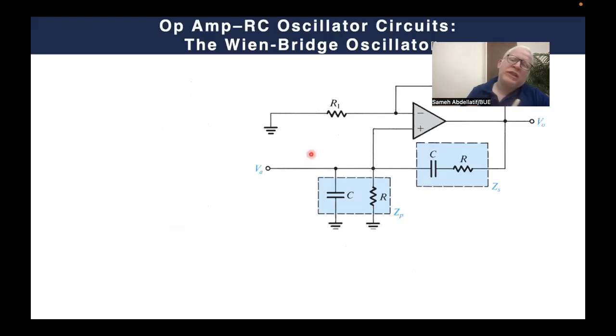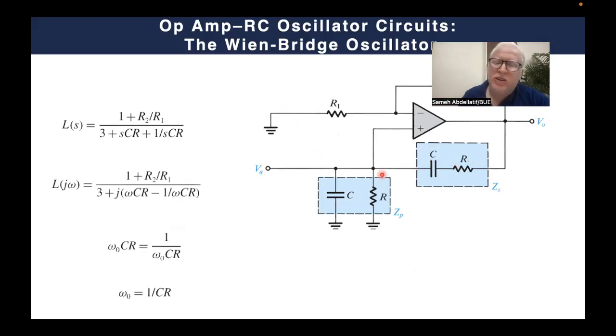And we also introduced another circuit to act as an RC frequency selection network. We introduced this RC network, where you just need R2 over R1 to be equal to 2 in order to get a typical A beta equals 1, which is of course applicable.